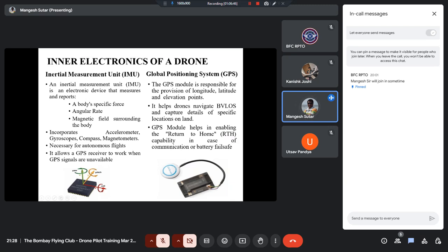These are very important when you are actually flying a drone. Telecom towers or power line towers lot of times radiate a lot of magnetic field around them. We have seen that when we are flying DJI drones, the basic drones like the Mavic or Air kind of drones, they get affected as we fly closer to telecom towers and wires, or even power line towers.